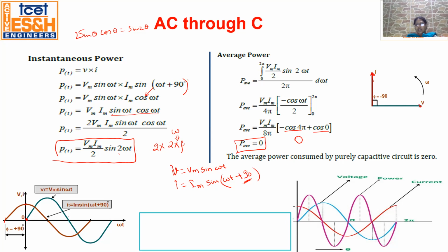Suppose here you see this is the waveform, this is the current, this is the voltage. Now V and I are positive; I is positive till here and V is positive till here. So the multiplication, power equal to V into I, gives positive power. So the waveform is positive. Now at this time, current is negative but voltage is positive, which gives negative power.